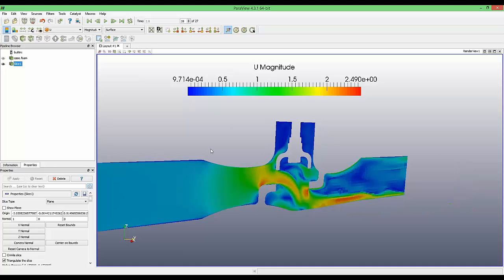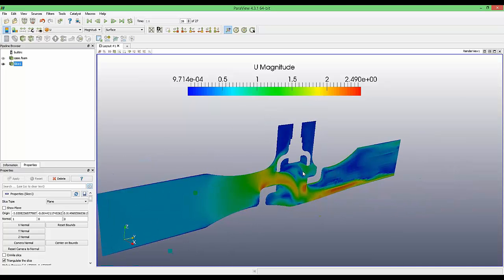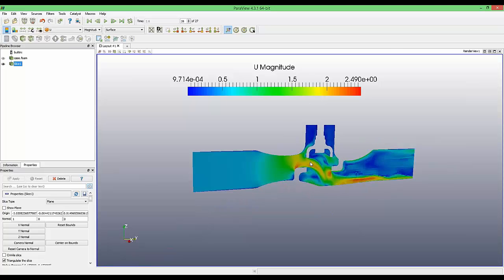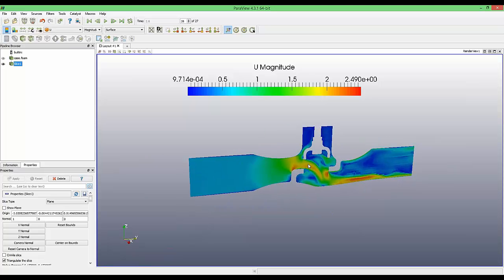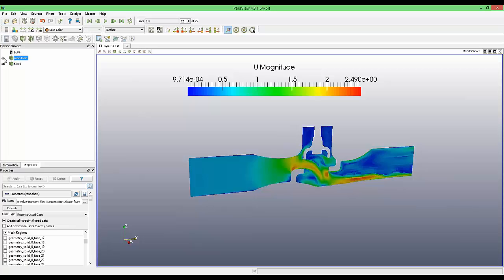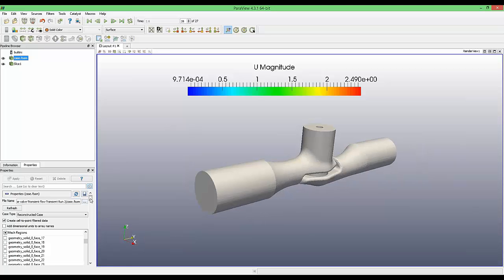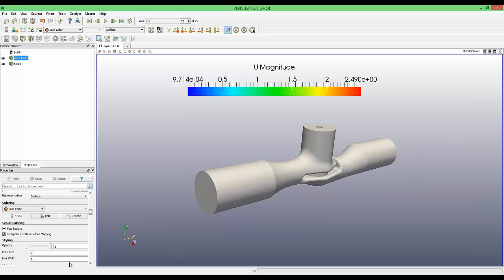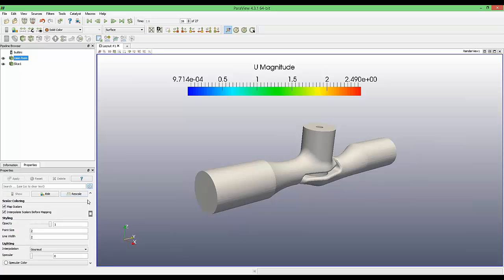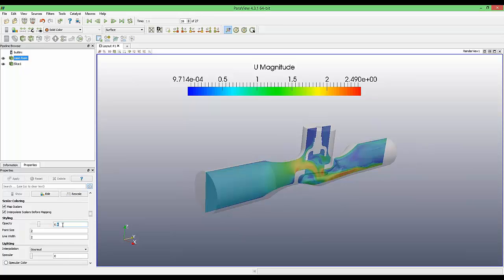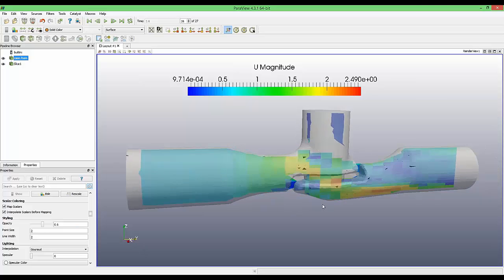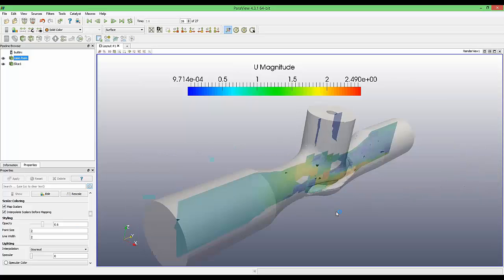Again, we would like to have the possibility of representing the rest of the data, or let's say having some more sophisticated views. What we can do is, for example, show the case and give it some opacity. You just scroll down in the advanced properties and find the styling menu, choosing the opacity. Maybe 0.4 is a little too small. We'll give it 0.6. There we go, a ghost body that contains our clip.